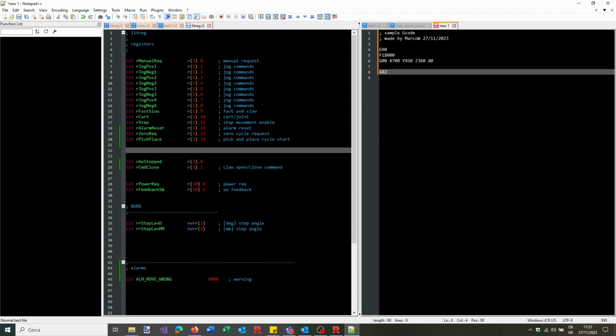I know that in some G-code this could be already a standard command for other kind of things. So if we want, we may just create our own M function like M182, and this could be, for example, a tool open. Then we should check in the task and later also write some piece of code to handle this.